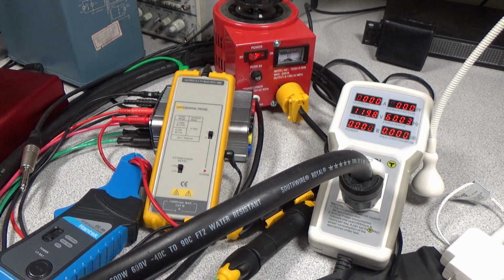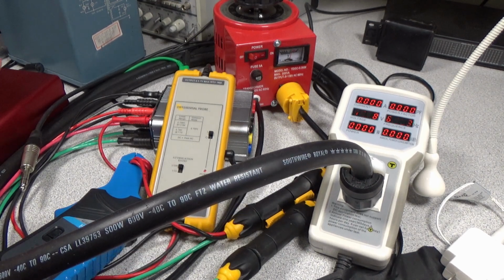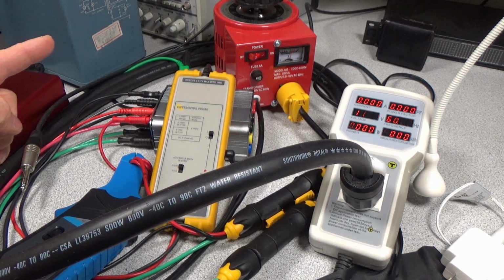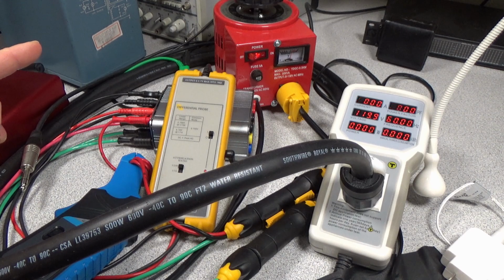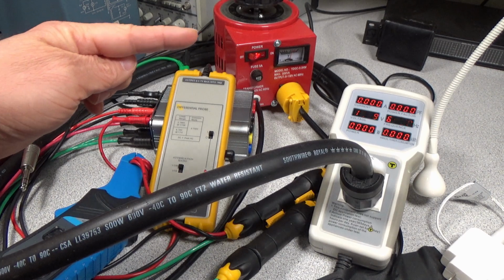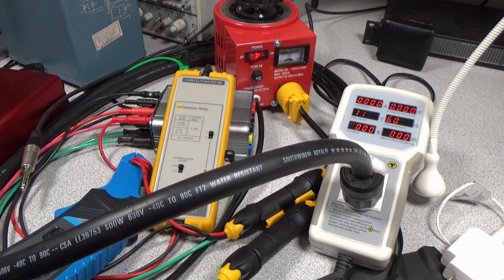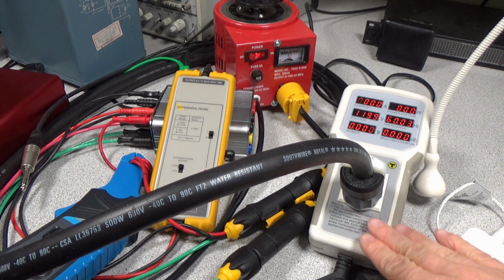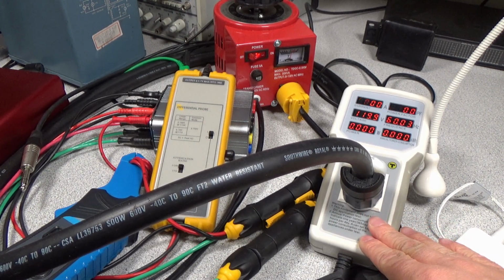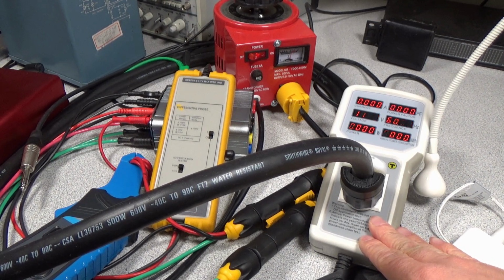So first thing we do is we have an isolation transformer, which is this guy over here. That's going around plugging into this red box over here, which is a variac supply, so we can just adjust the voltage, get it as close as we can to 120 volts just for somewhat even comparison. And then sensing the voltage. So we're going into this next. This is just a little, really cheapo power analyzer, nothing fancy, but functional enough.